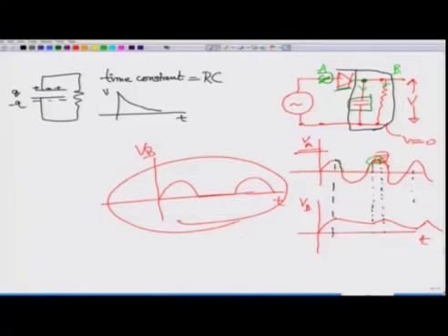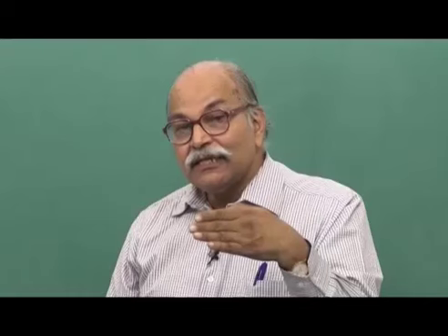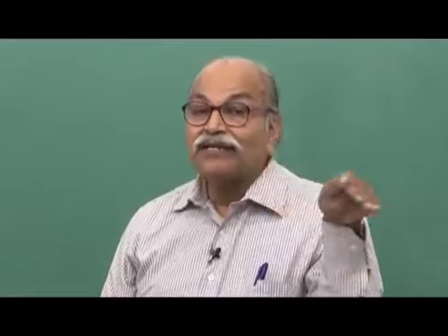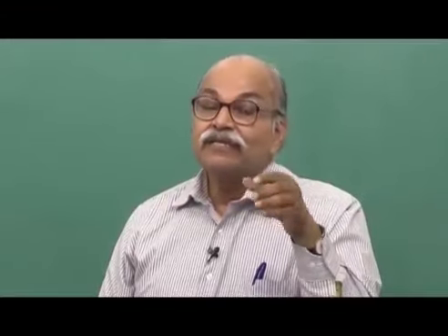You have this voltage which is going up, coming down, becoming 0 for a lot of time, again going up, coming down to 0. Compared to this, see this voltage here, compared to that it is a much better DC. So, putting this capacitor here, it is a kind of filter. It makes your DC a better DC in the sense that fluctuation about that average DC is reduced.